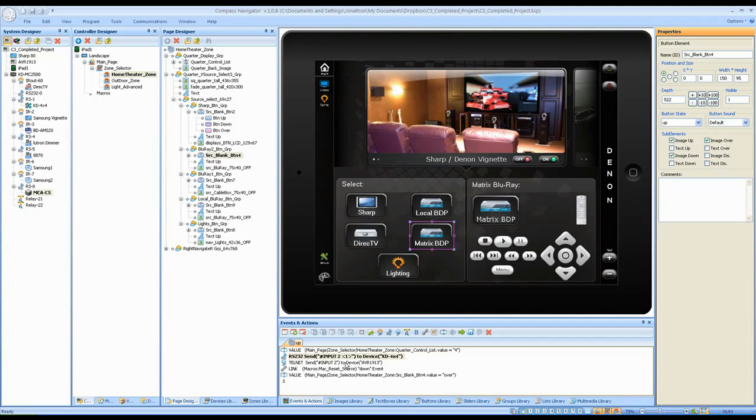We are also ensuring that our AV receiver that is part of the system, so actually the matrix feeds the AV receiver, is switching to its appropriate input. This is the matrix feed was input number 2. We're linking to that macro that reset all these other buttons into the up position, and we are putting this button itself in the over position. So you could have done it as this element equals over, or in this case we did go through and pinpoint what element we're controlling, which is this source underscore blank underscore button 4. Okay, so there's an example of the RS-232 command.